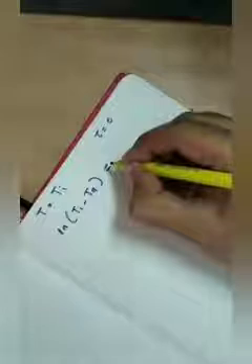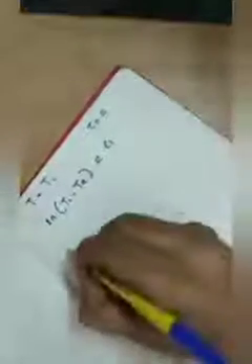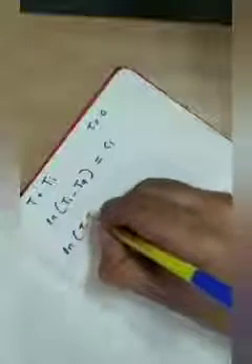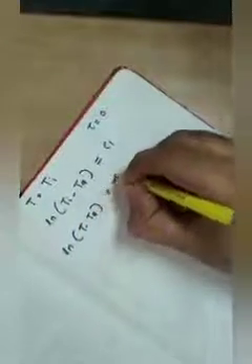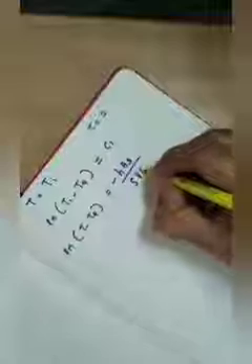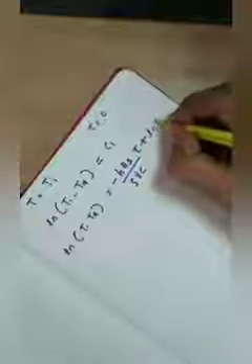So we have got C1 as ln of Ti minus Ta. The solution is log of T minus Ta is equal to minus h As by rho V c tau plus log of Ti minus Ta.